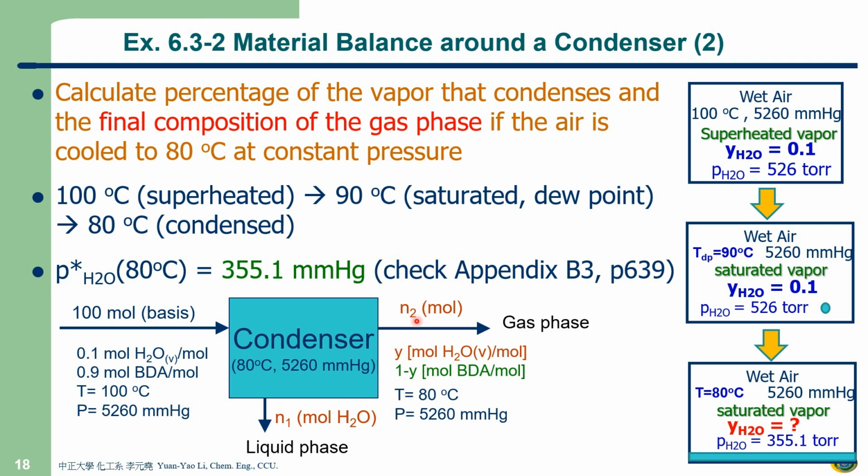Yes, because how many equations do you need to get? 3 equations. How many species here? 2 species, air and water. So you already have 2 equations. What's the third one? Relationship with what? With the Y and the TP. This is what we call Raoult's law. So the third equation uses Raoult's law to find the molar fraction of the water in the vapor phase.